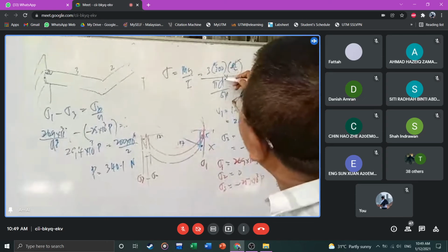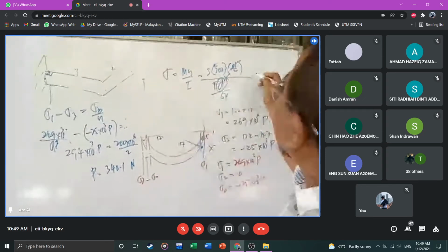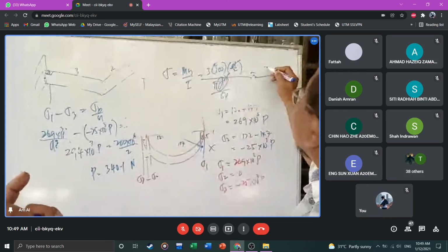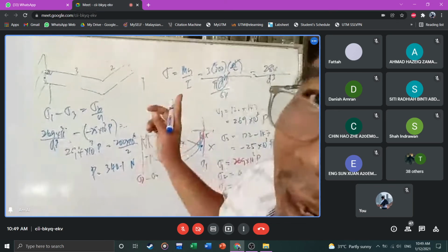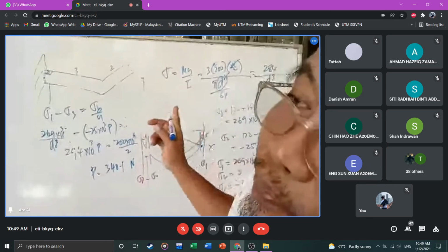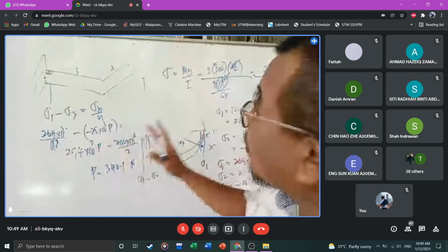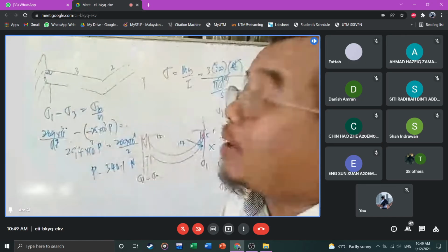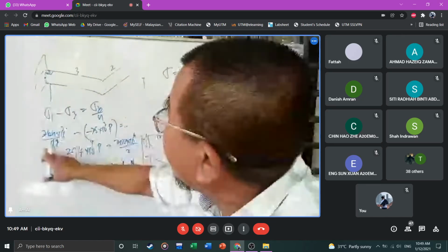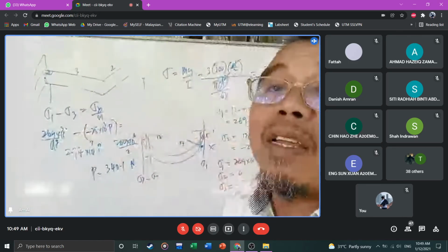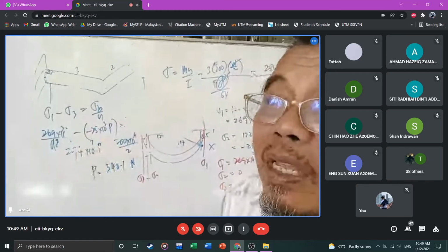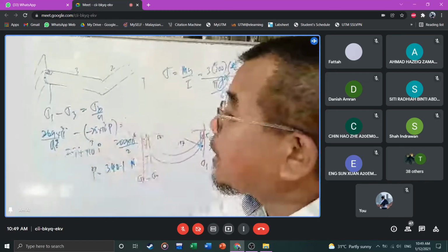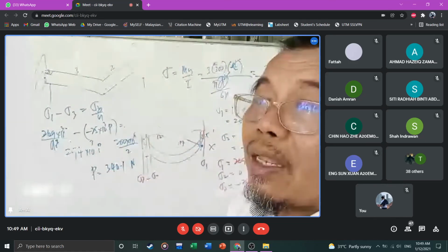And then d and d cancel here, that's why your unknown is numbers here, 248 over diameter cubed. Can you see that written there? The unknown, you bring all together there, and then you solve at the end. You can solve your diameter. But the procedure is all the same. You draw the Mohr circle in terms of d to the power of 3, in terms of P.